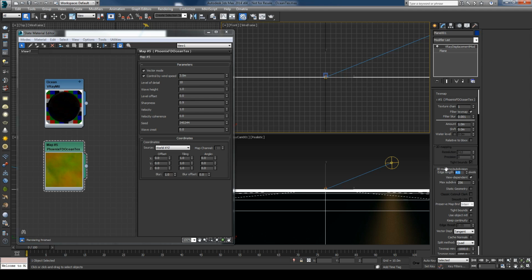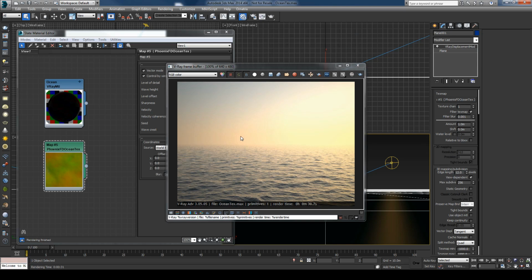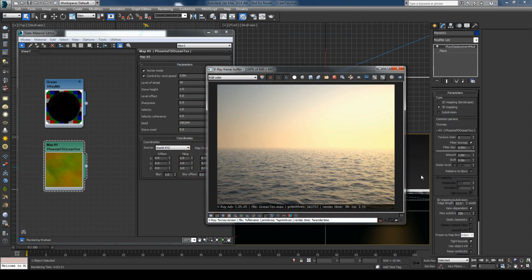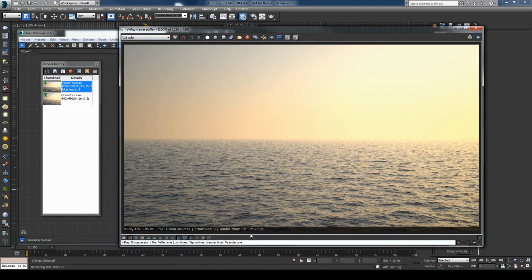And for now, I'll just set it to something higher, like 12, and hit render to see the result. And it's done in 30 seconds. So I'll just try now with the edge length of 4. So I'll set it to 4 and re-render. And with 4 it definitely looks much better, but it comes with its price. From 30 seconds render time, it's now 1 minute. I've also rendered it to half HD, and again with 4 segments, and it rendered in 3 minutes.